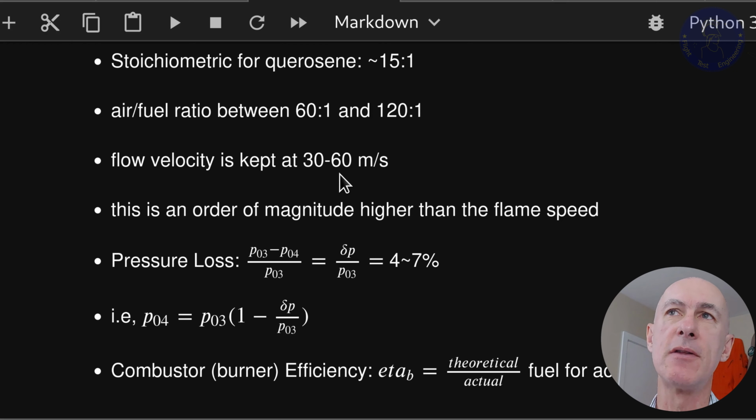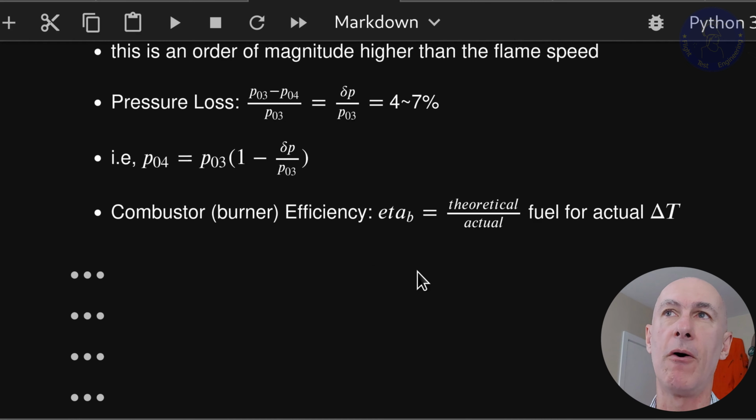You see, this in fact is the main reason where there is pressure loss in the combustion, which is friction. The swirlers, tangential injectors, and all of the turbulence that is created end up dissipating a lot of energy in form of friction, leading to between 4 to 7% loss in this sense, which is a lot. It's not small. The other source of pressure loss is due to the rise in temperature, which brings down density, and since mass flow does not change, the flow velocity needs to increase. Now, to increase velocity, there must be a delta P pushing the fluid forward towards the exit.